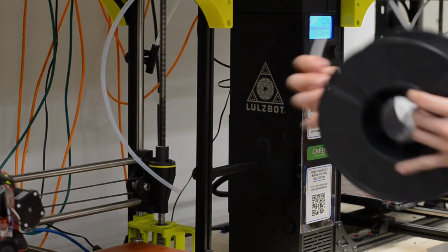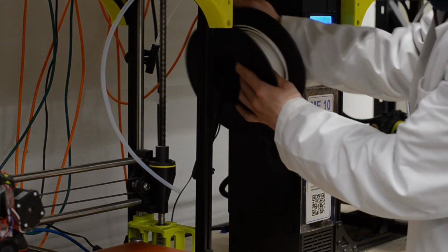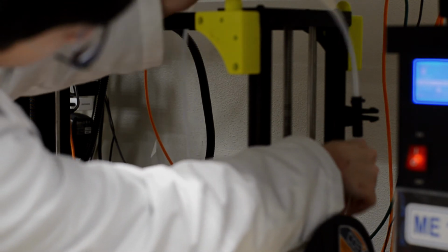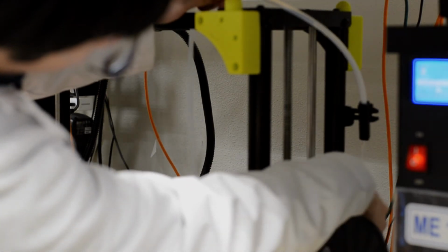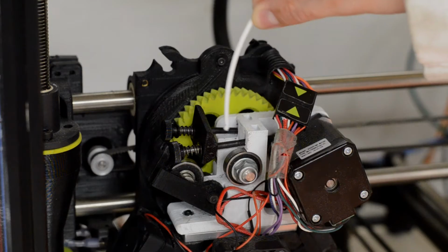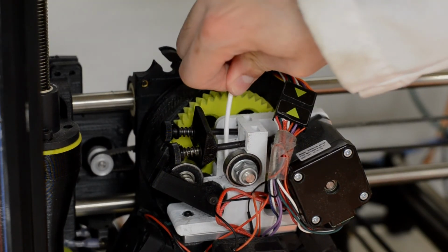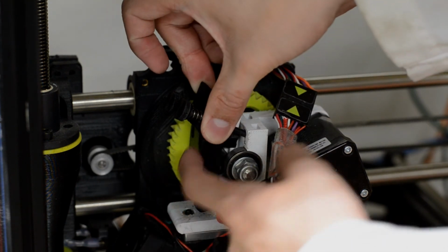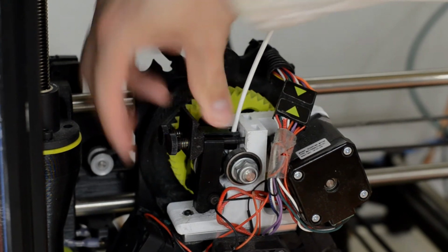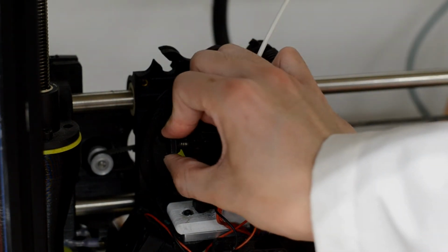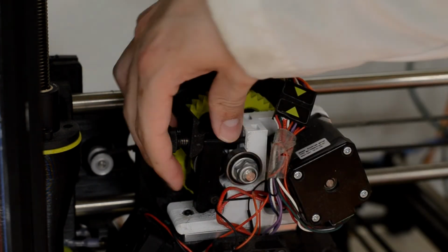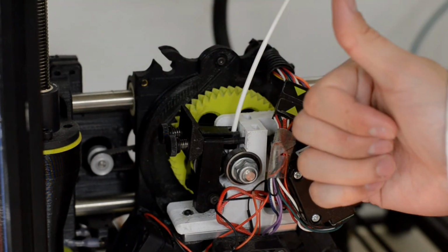We're going to take our filament and put it onto the arm. String the filament through the tube located next to the side of the printer on the back, and we're just going to keep pushing until you see it come out the other side. Once the filament has come out the other side, we're going to put it in between 2 screws. There's a hole there. We'll just have to locate it by itself. You're going to push that latch up, push the wheel in, and then drop the latch over. There should be spring tension, and if there's not enough spring tension, you should turn the wheels righty-tighty, lefty-loosey. Without the spring tension, the print will fail, and that is our most common cause of failure.